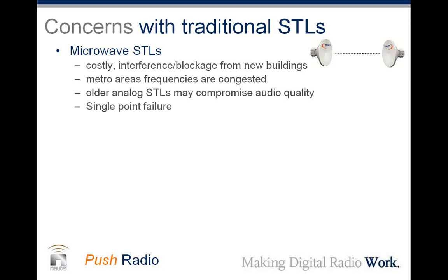And these traditional STLs are a single point of failure. If they go down, the whole station goes down. Even though you may have multiple studios in your transmitter site, or you may even have main and alternate transmitters, you have a single point of failure in many cases in the studio to transmitter link.